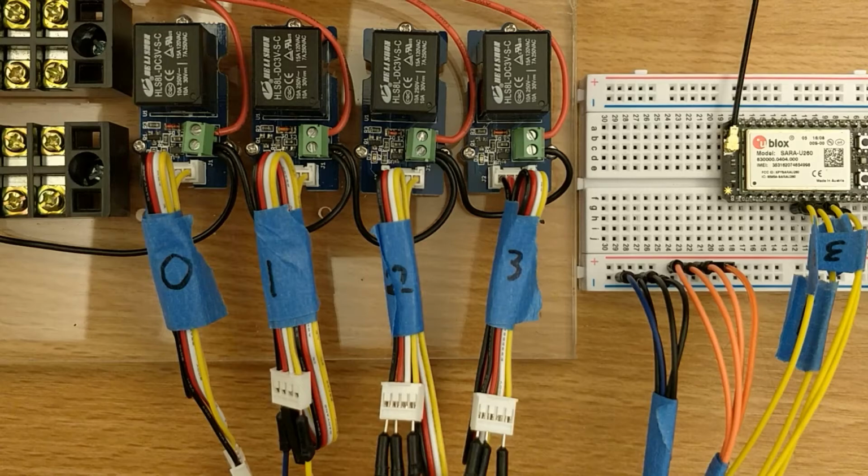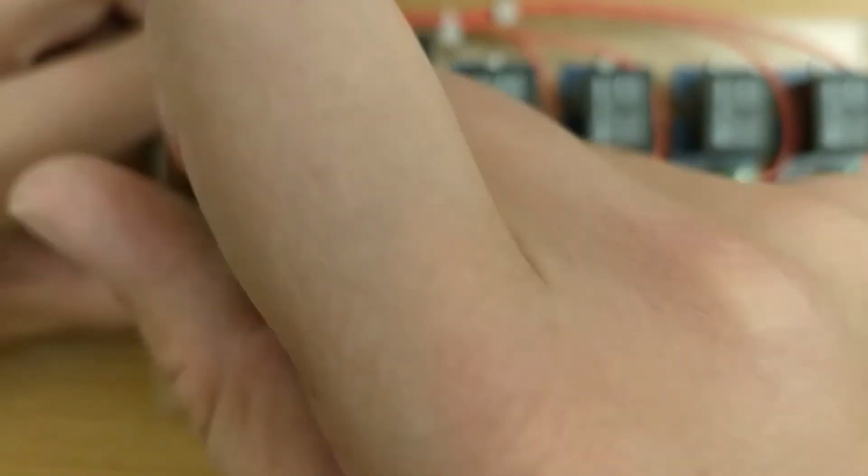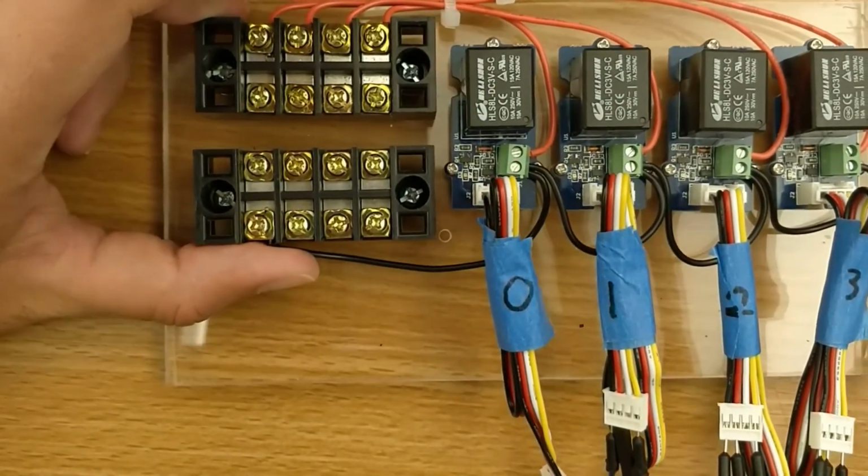Now that we know how to turn the relays on and off, I'm going to show you how to wire up the relays with an actual LED. I'm not going to hook it up so that each relay is connected to an individual LED. I'm just going to use the same LED over and over again and plug it into different spots. So, to start out, I'm going to go over here to where common is connected and unscrew that a little bit, make sure it's loose.